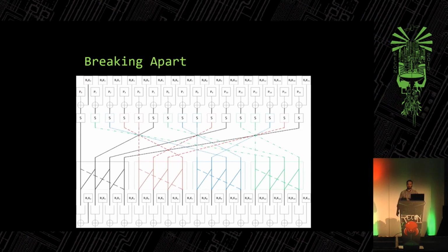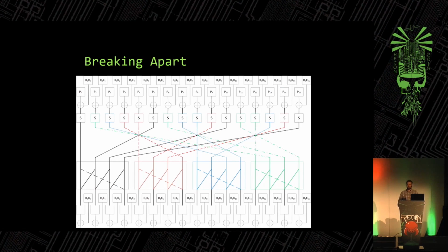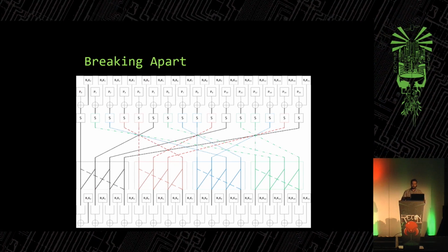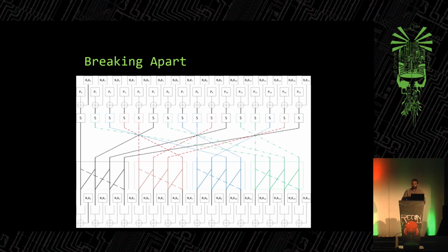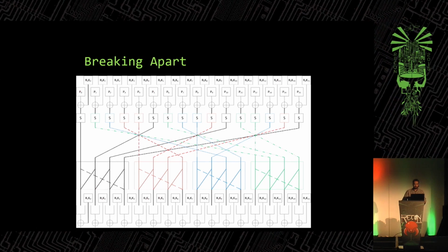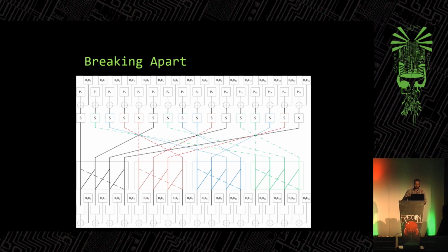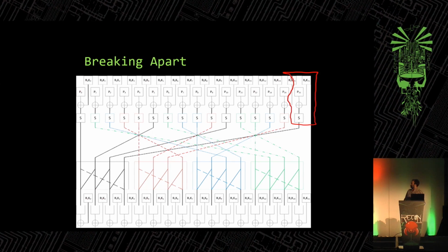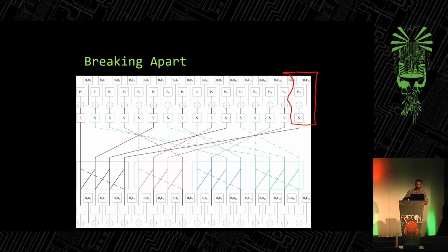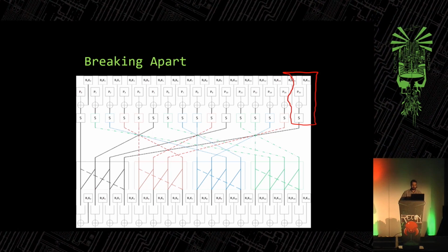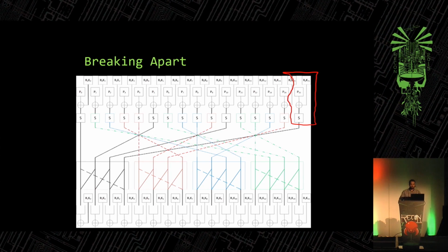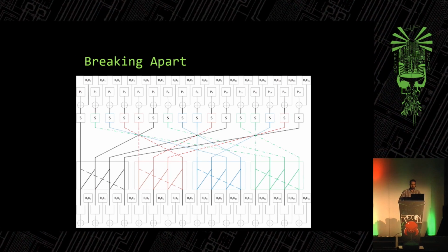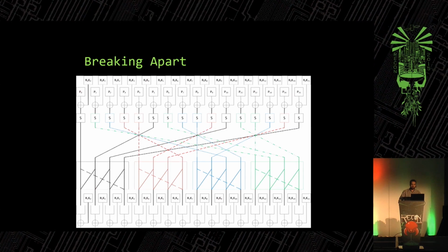Why this is useful to us is if we look at a lot of algorithms, so again, going back to AES, it's a 128-bit key, so we can't guess the key any way we want. But what we could look at is, well, it operates on 1 byte at a time. And if we just concentrate on one little section of the algorithm, so if I just draw a crude square or rectangle around that section up there, what the power analysis will tell us is that we're going to look just at this point in the algorithm. We're going to look at the data right at this output here.